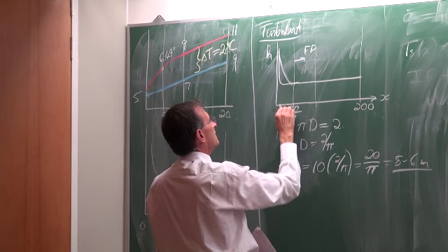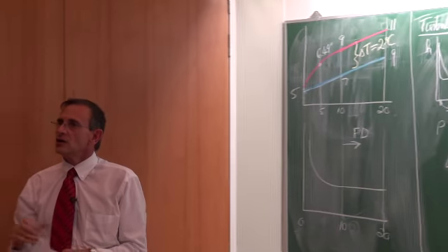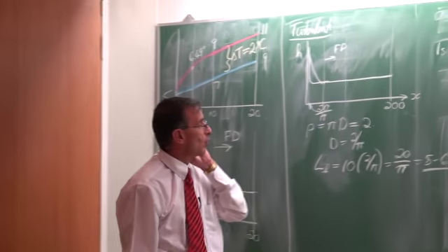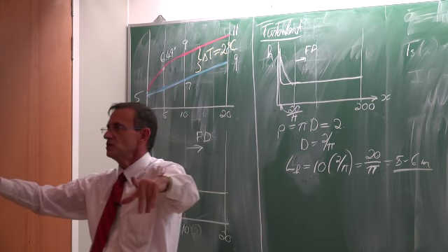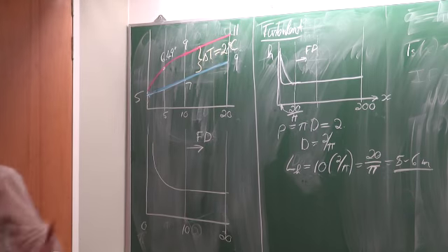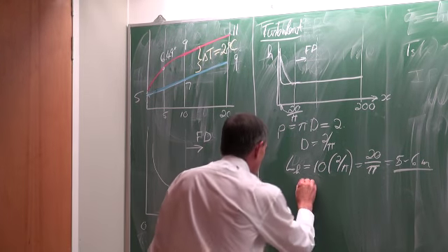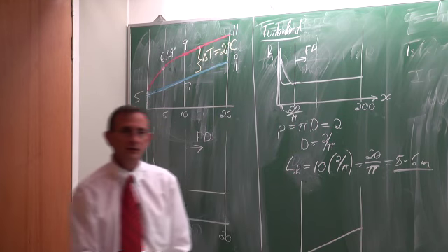And then that value would move to that point there. So it would be quite a good and a very reasonable assumption to say the flow is turbulent, which means the heat transfer coefficient is almost a constant right through. You agree? So then the result would be that our fluid temperature would do that.